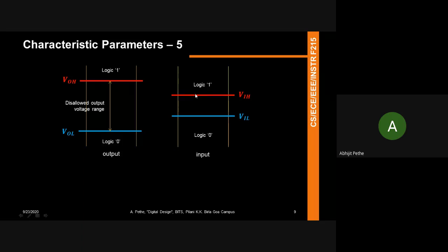And so what you see is that you talk about two noise ranges, a noise high and a noise low, right? These two are what are known as the noise margins in the logic family. My voltage at the output of one gate can reduce by VNH and still be treated as a valid high.